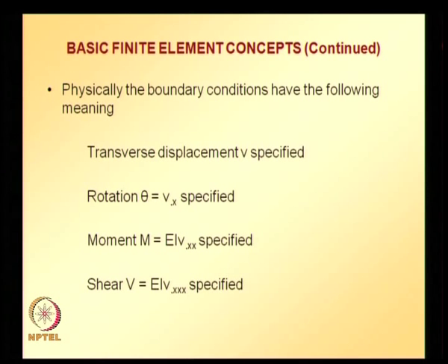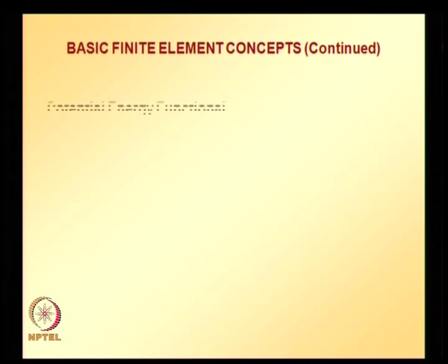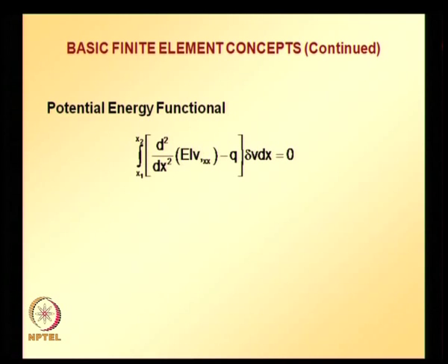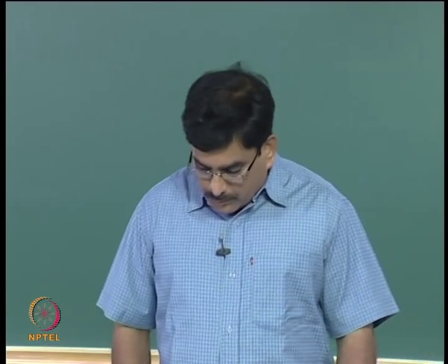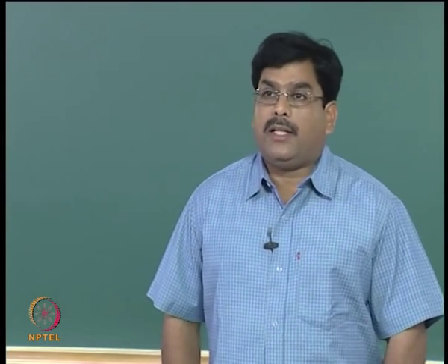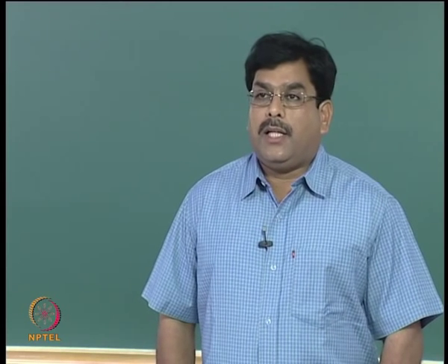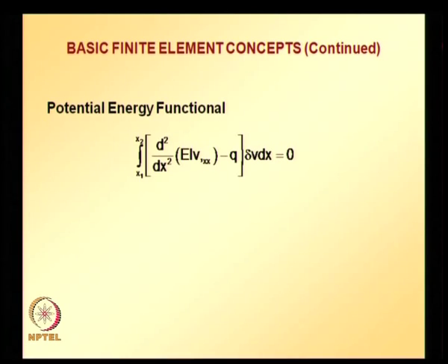So, the procedure is as follows: multiply the given differential equation with the variation of transverse displacement, and integrate over the problem domain. Here the problem domain is taken as x1 to x2. The next step is, for any of the terms having higher order derivatives, we can reduce the order of derivative by using integration by parts.